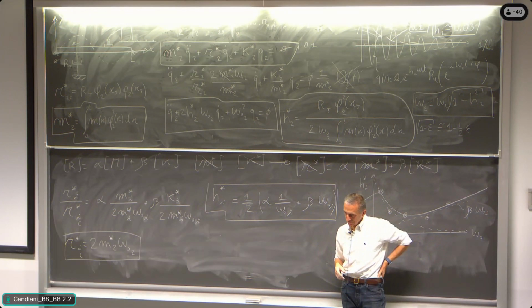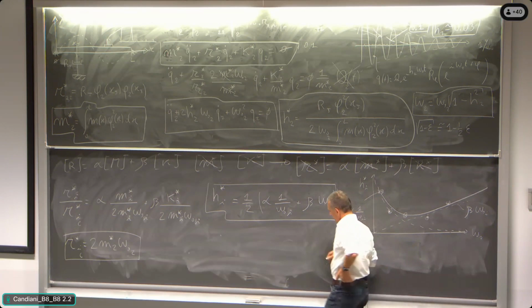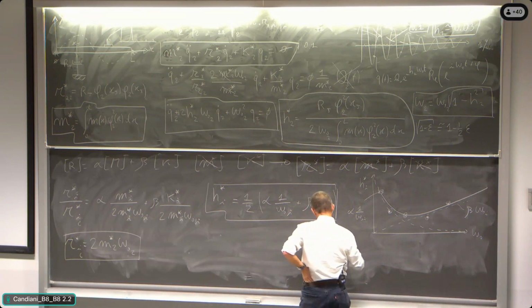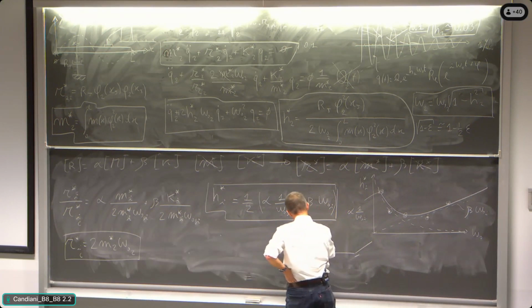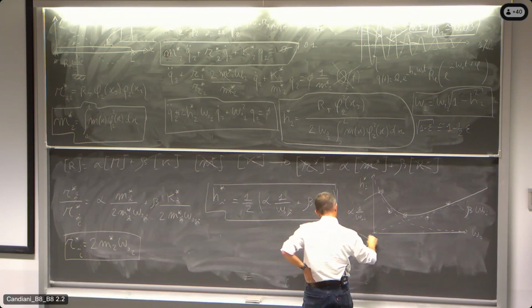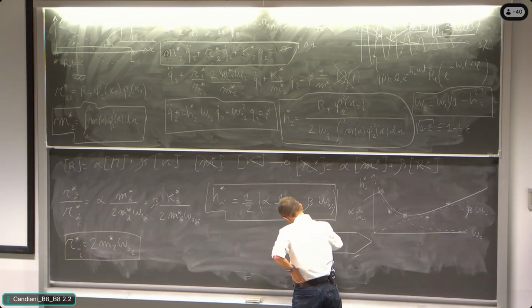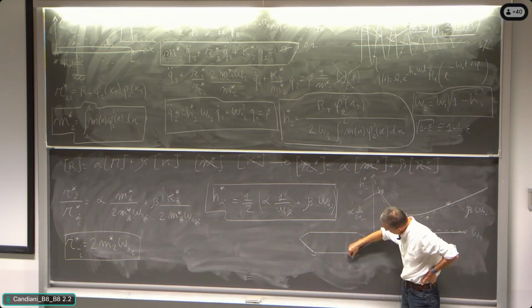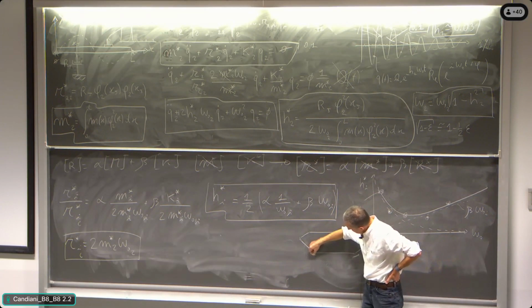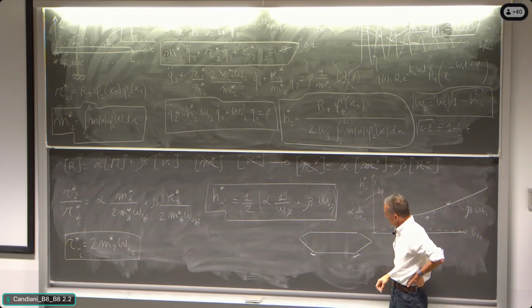At the same time that it was built, it started moving because of vortex-induced vibration. And then it was fixed by guide vanes positioned here and there. It was a little bit expected, but anyway. It started vibrating as soon as it was built, and then the guide vanes fixed the problem.